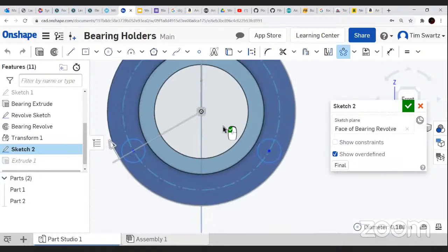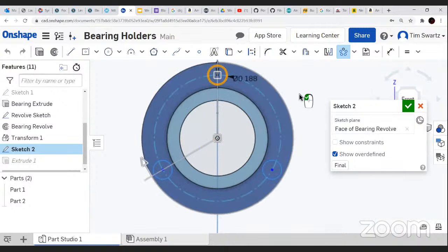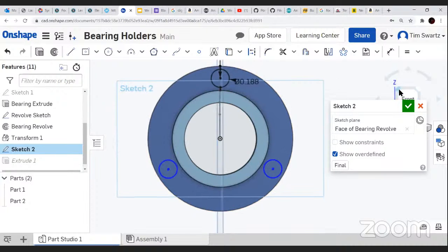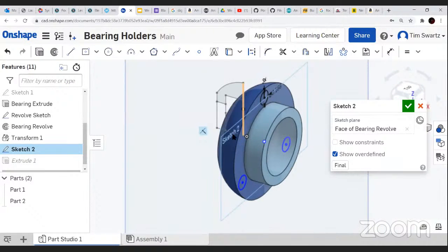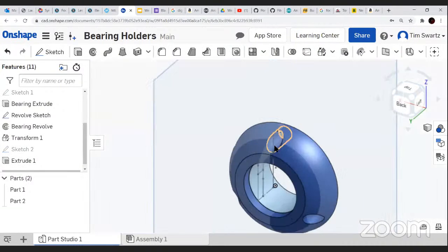And if I wanted more holes, I could just adjust the value here. See how it says 3x? I just come here and type 4 if I wanted 4 holes, or however many holes you wanted. I just want 3, and they're going to make them equidistant. Then I just right click and it's there. Then I just drew them out. You can see that here.